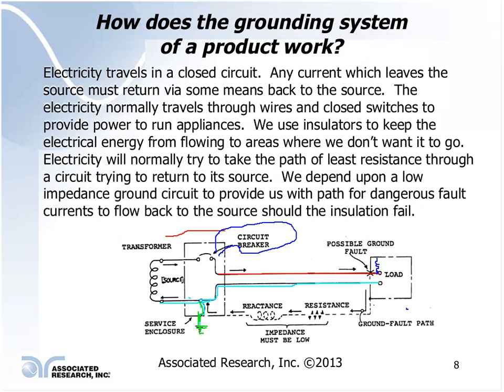But as an example, this circuit breaker that we have here, if this is a 115 volt circuit, if we're talking household circuits and fuses and circuit breakers, this circuit could employ either a 15 or 20 amp circuit feeding power into the receptacle that we could plug our products into.